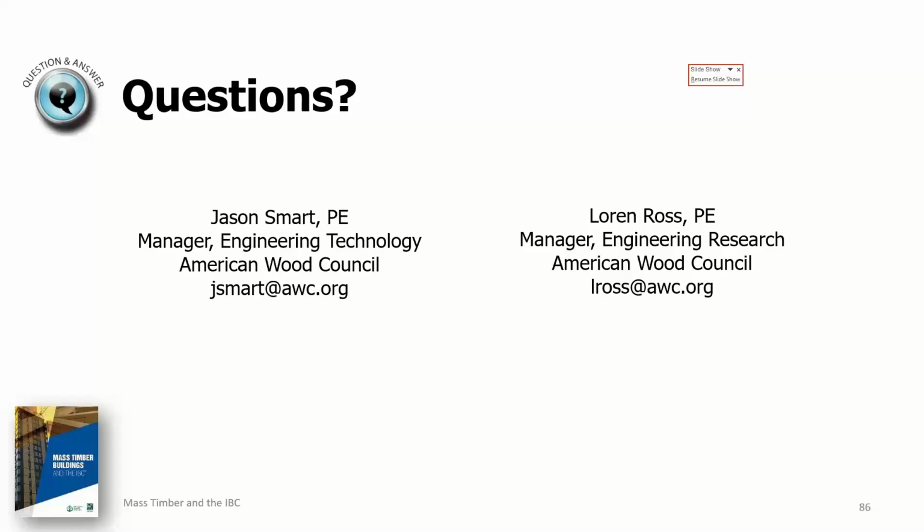Yeah, communication, as I mentioned in one of those slides, does require communication with the manufacturer in that particular case, because it's got to be manufactured a certain way to achieve that fire resistance rating. But if it's specified in accordance with 16.2.4 of the NDS, the glulam manufacturer should know exactly what to do with that.